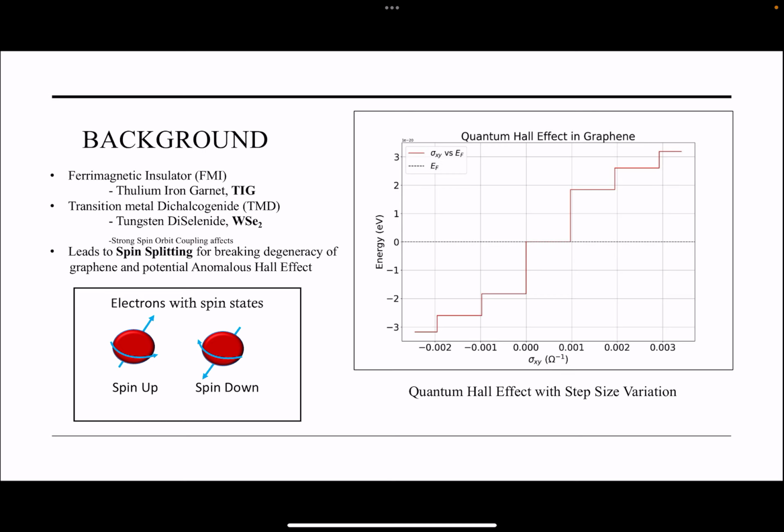Another material we hope to pair with graphene on the upper level of it, WSe2, or tungsten diselenide. This will help us create a spin orbit coupling effect within each atomic lattice structure. Now, what this entails is that this opens the possibility of opening a band gap within our devices and introducing spin polarization, which we will get into more detail in a little bit.